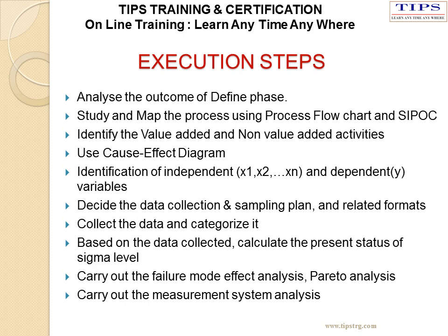plan for collection of the information based on these independent variables, that is critical variables, and related formats, collect the data and categorize it. Based on data collected, calculate the present status of sigma level. Carry out the failure mode effect analysis and Pareto analysis for scrutinizing and shortlisting the causes of variations or problems for further analysis. Carry out the measurement system analysis to know